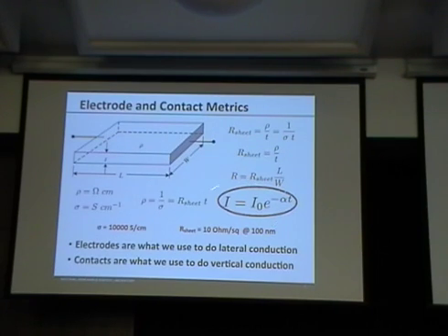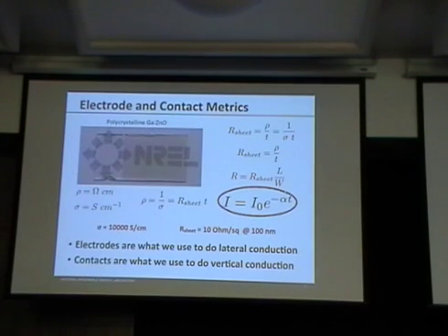And the other thing I need to think about is the optical transmission, because when I make something thicker, I'm going to make the optical losses worse if I keep everything the same. Which is why, when I showed you this, this is an 8,000 Siemens per centimeter piece of GZO, gallium doped zinc oxide, but it's also 500 nanometers thick, which puts me in the 2 ohms per square kind of sheet resistance. But it is a little bit lossy. So these are the considerations.